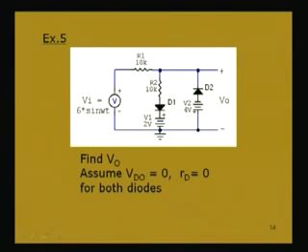Now, you have to be careful because we have two batteries, 2 volt and 4 volt, connected in this fashion. With D1, the 2 volt battery is there, which is reverse biasing this diode, and this 4 volt battery is also reverse biasing this diode D2. So, both these diodes are reverse biased by these two batteries. So, now when will it be conducting?